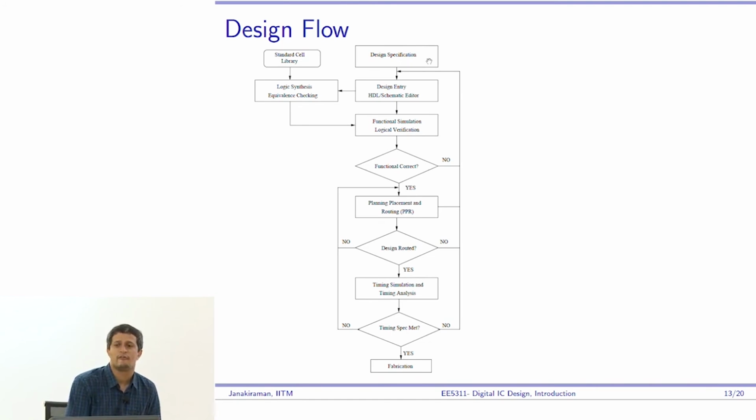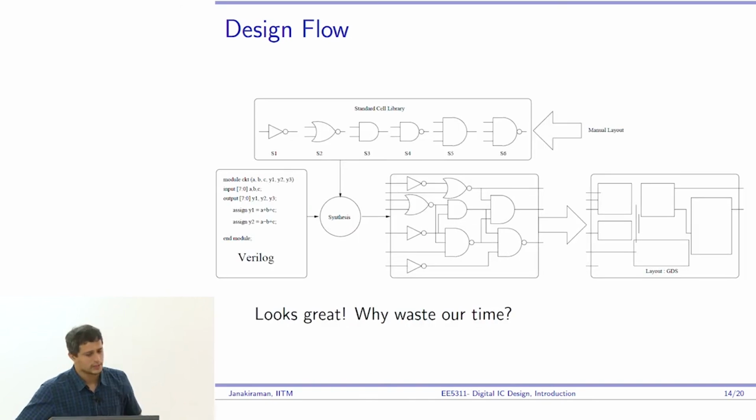Digital IC design is a very fundamental digital circuit design course where we are going to deal only with transistors. And that's what I'm going to teach. So if you look at the design flow, you have something called Verilog code here. Then you have something called a standard cell. A standard cell is basically a set of gates which have been designed, hand laid out and given to you, saying, look, these are my universal gates. Now you have to synthesize your circuit just with this.